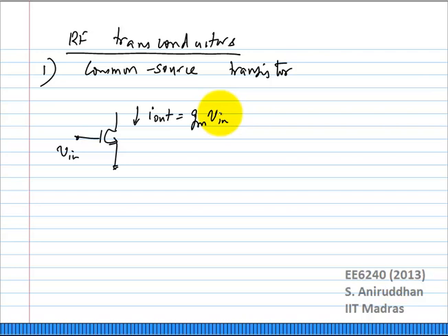Let us say the transconductance is perfectly linear. Does that mean your overall mixer is perfectly linear? So far as we have seen, yes. Right? If your conversion from VRF to IRF is perfectly linear, we have seen that if the mixer has ideal switches, it is just a multiplication and there is not much more to it. Unfortunately, we do know that these mixers, if you use real devices, will not be ideal switches, and there could be some hit to linearity. We are going to look at that today.